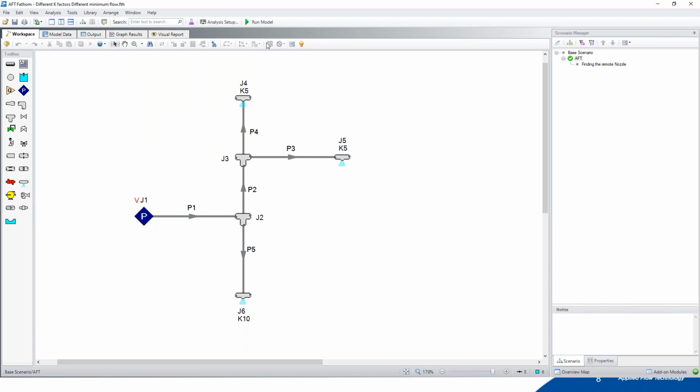The next step is to activate the GSC module. So in Analysis, you go to Goal Seeker Control and you tell it to use it. If you choose ignore, it will not iterate for you. The next step is to go to Goal Seeker Control and create the variables.